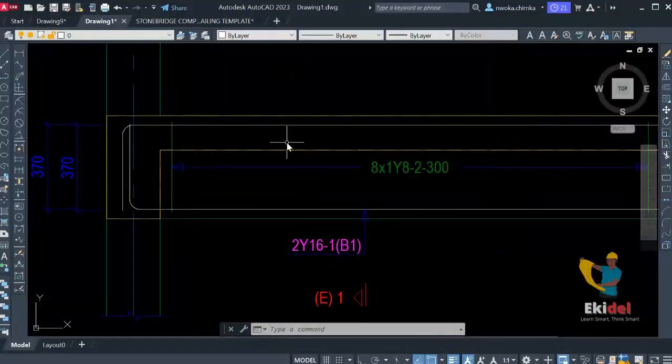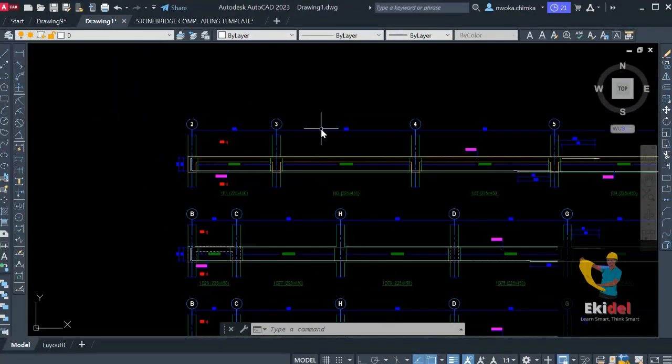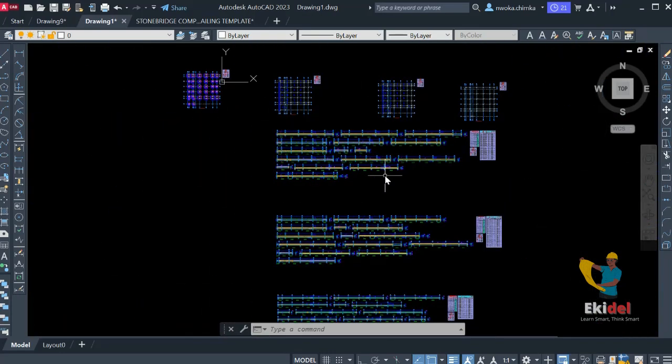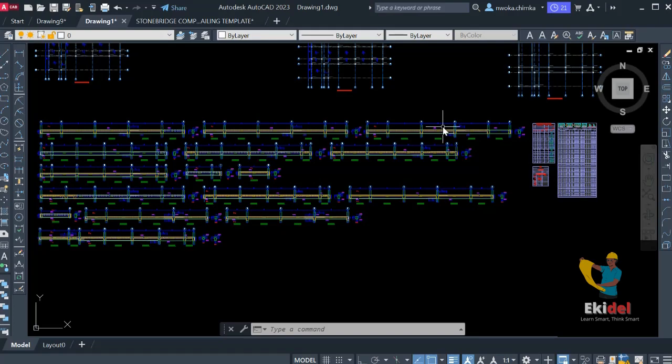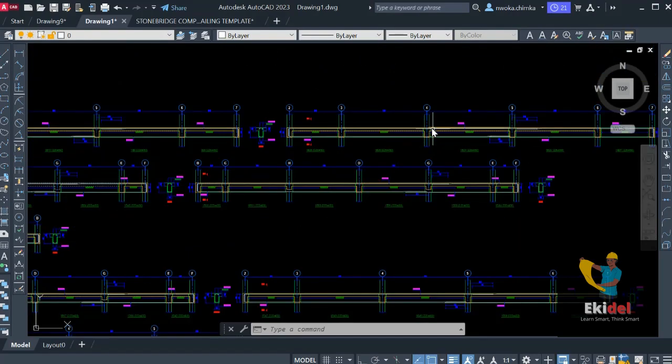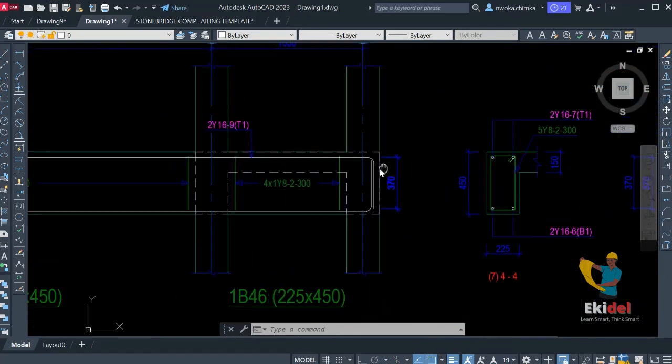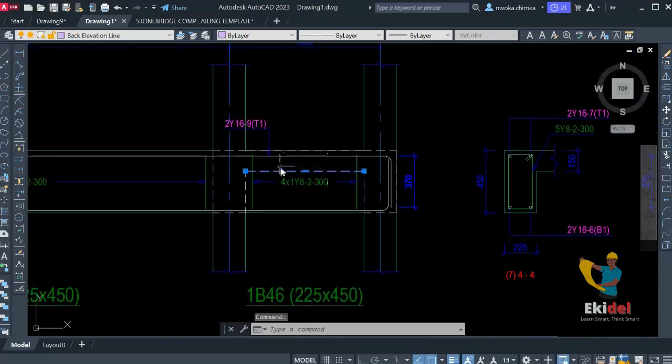Now, you can see that a lot of work is to be done here, because if you print this directly without doing any other settings, without touching the layers and doing a proper detail, you can see that Prota Structure brought some things that are not necessary.